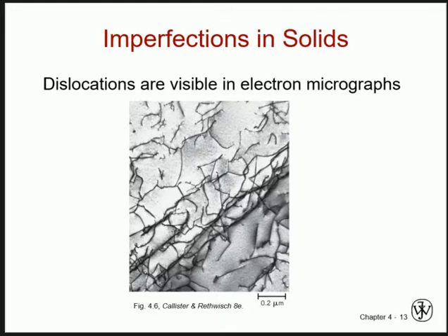Rather, they will move only in the energetically favorable directions. Energetically favorable means the direction in which it is easiest for the atoms to move. They're going to move in that direction at low stress. So if the atom has a possibility to move in a direction in which less force is required, it is going to deform and move in that particular direction. Those directions are defined by Miller indices within a crystal structure.